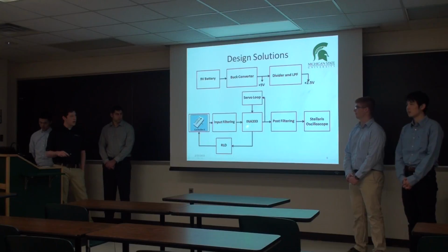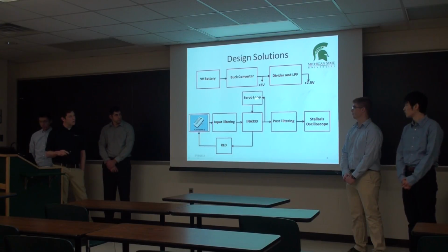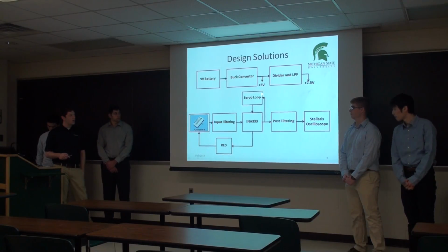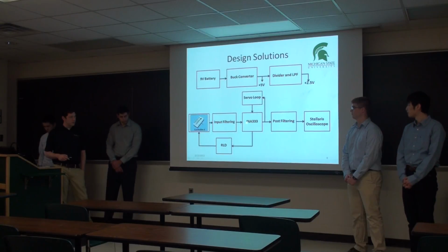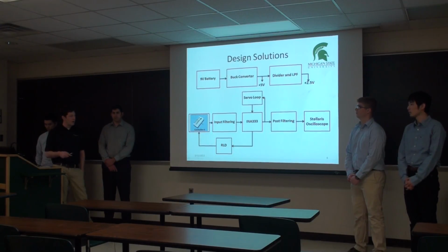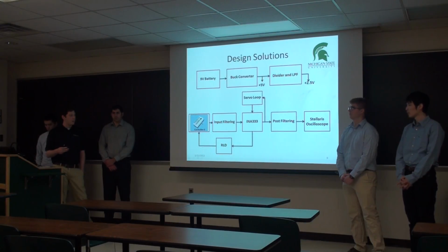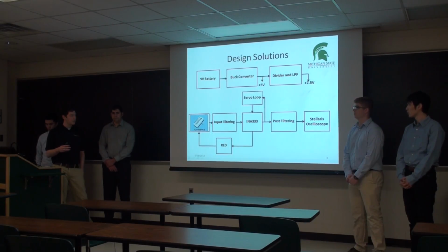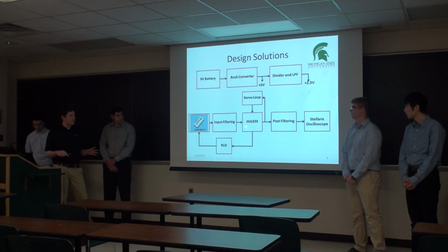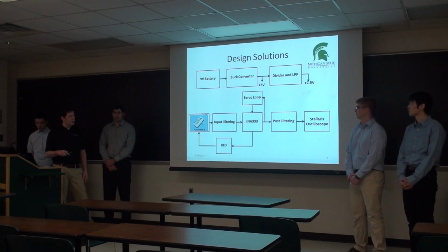From there, it goes into the INA333, where the servo loop acts as a filter for getting rid of DC drift. It's a low pass filter and an integrator, which feeds back into the reference pin of the INA333. Overall, the INA and the servo loop together become a high pass filter, getting rid of the DC. It passes the 3 to 10 hertz range, somewhere around there, through the INA and amplifies it.